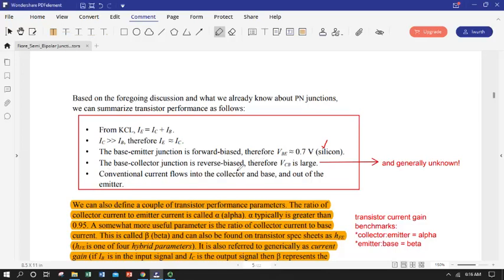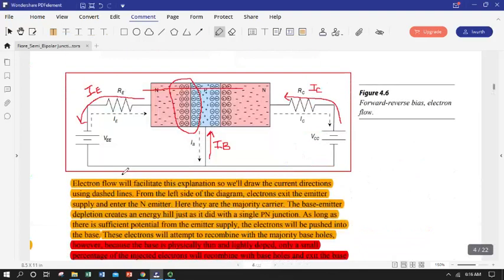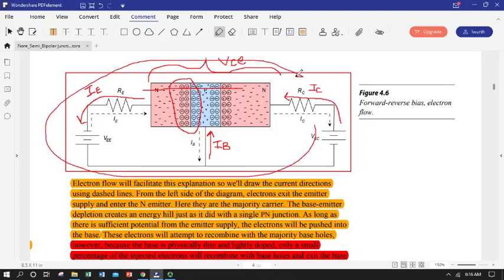And in fact, what we're going to solve generally by difference is the voltage drop all the way across the device. We're going to get the collector emitter voltage when we look at these in circuits. VCE is what we're going to solve for. So we're going to end up having two loops: the big loop we're controlling, and the little loop that's our signal.